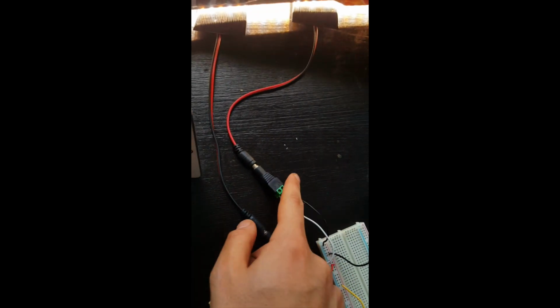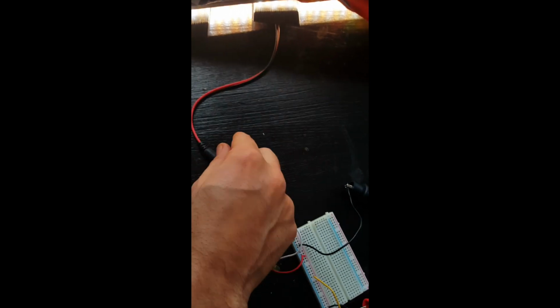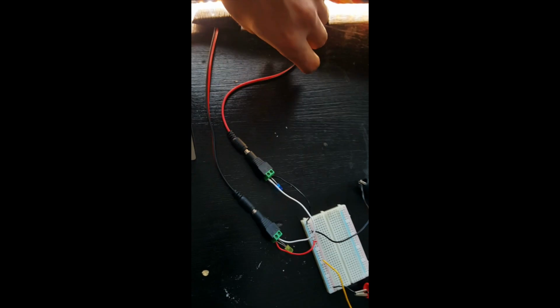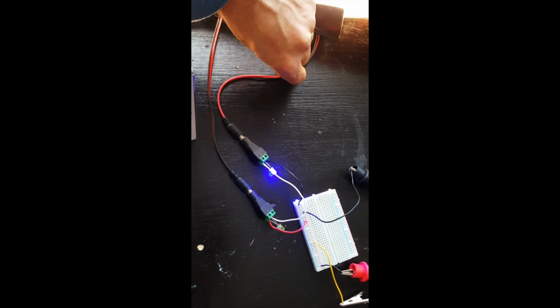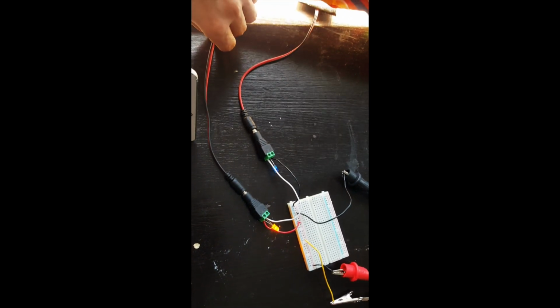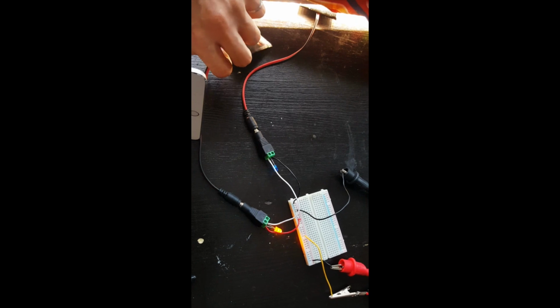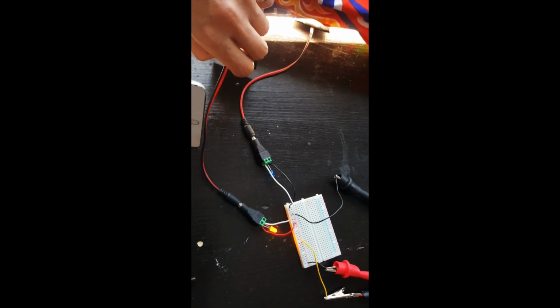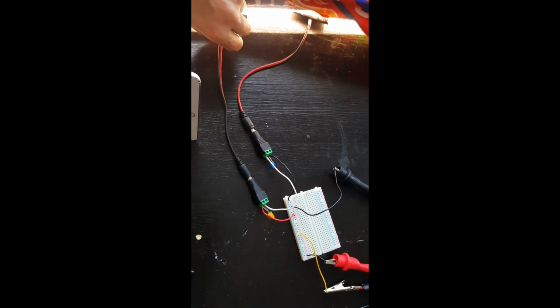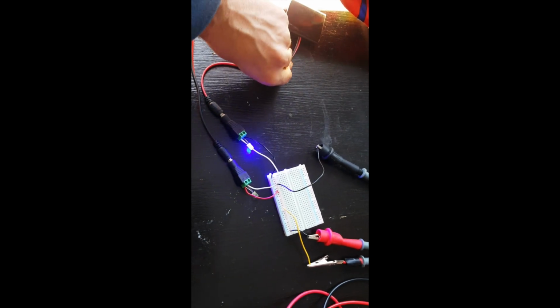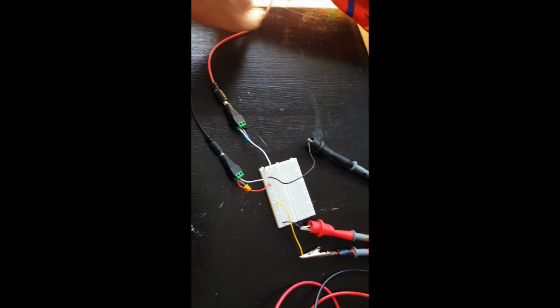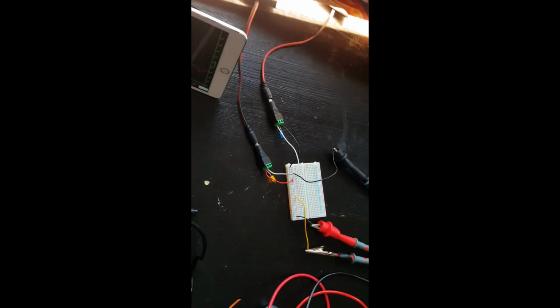Let's see if I can pull. So let's pull this blue one. Let's see what happens. Oh, the LED turned on, which means it's conducting. And let's try with the other one. Oh, it worked on its own. And the more I pull it out, the brighter it shines because the more current's running through it. If I bring it back, they'll go dark. Pull the blue one out. So we know that the bypass diodes are working.